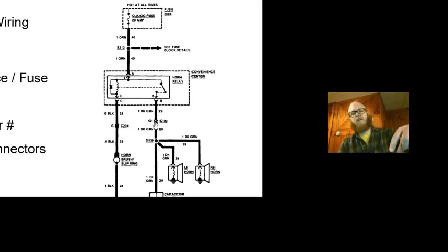So the way that this is looking is it's two chevron looking things. And what we got on here is the male side of the circuit's on the bottom here. So that's the male pin that would slide into the female pin. That's really convenient, because if I'm looking to see if I have power here, it's nice to know what side of the connector I would expect to see it on. So I'm not like, well, test here. Nope, I test here. Nope. Okay, well, I don't have it, but I don't really know which way on this harness I need to travel, right? So they're trying to give us as much information as possible.